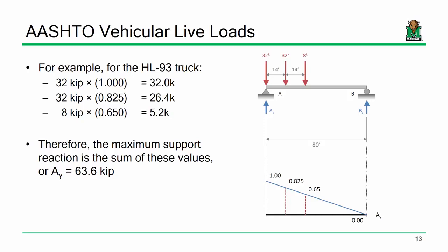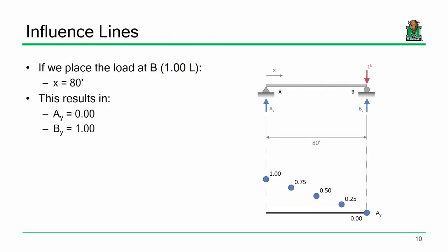Ignore what's going on with the slide, and let's just do a basic example. So let's say I put 20 pounds right smack dab in the middle of this table. How much goes over here and how much goes over here? 10 pounds. Let's say it's 180 pounds. How much goes here and here? Okay, now how are you doing that? You're just taking it and dividing it by 2, right? I propose what you're doing is you're taking it and multiplying it by the value of the influence line at the center, 0.5.